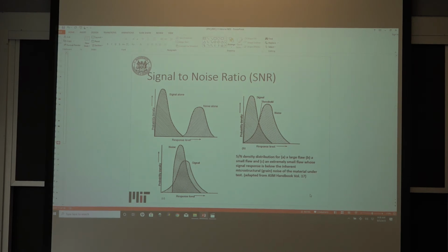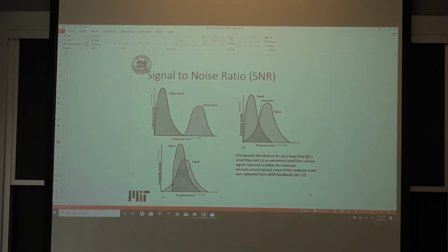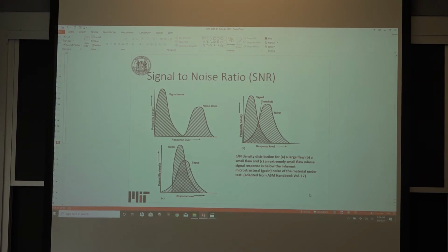And that's important to know because I deal with NDE a lot and I see a lot of new equipment coming out, and a lot of these techniques will claim that they can inspect things that they really can't. It's not the fact that they can just inspect it, it's can you reliably detect this flaw size? So that's why it's not the smallest flaw that you should be looking at in their brochures or published data. It's at which flaw size can you meet the confidence level requirement.